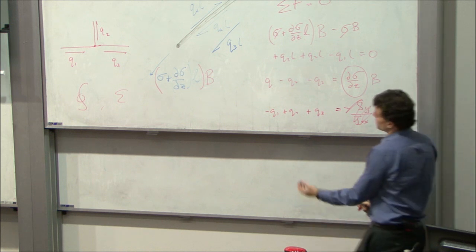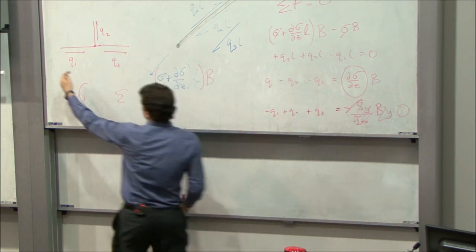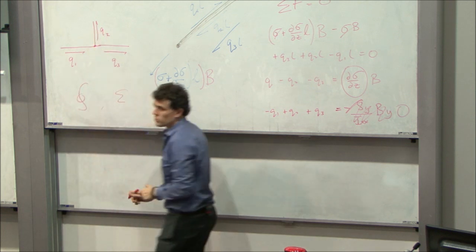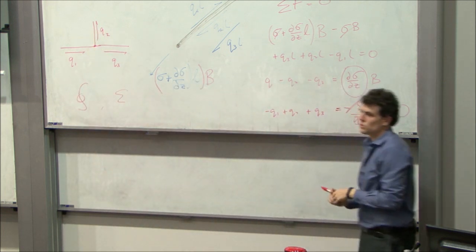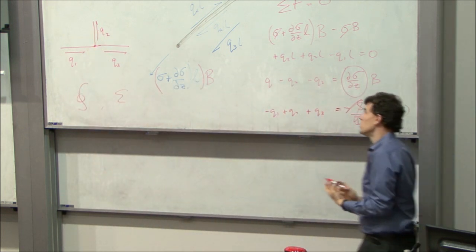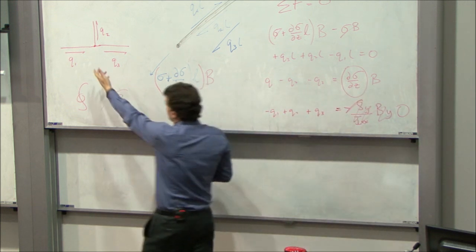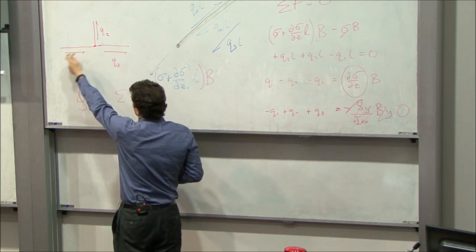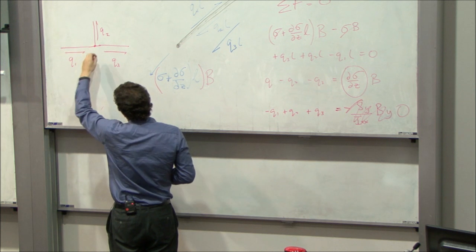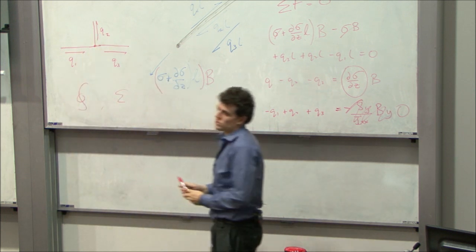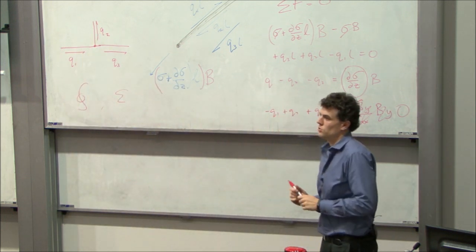And you can see that the sum of the shear flows coming in has to equal the sum of the shear flows going out. So just like current flow, in a non-idealized structure, sum of shear flows going in equals sum of shear flows going out, just like a joint in an electrical circuit.